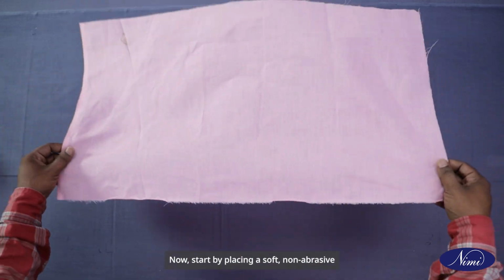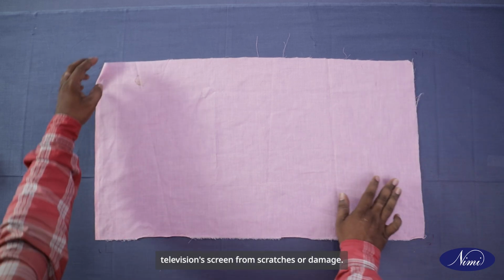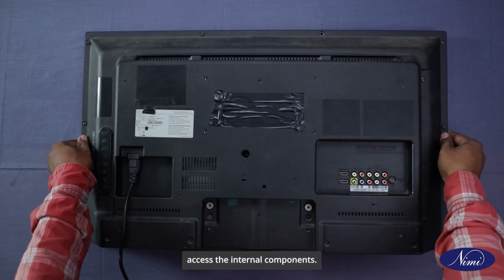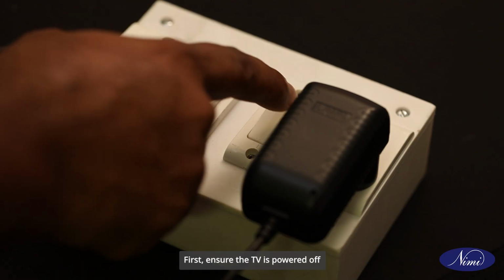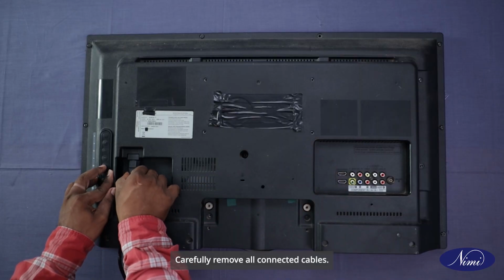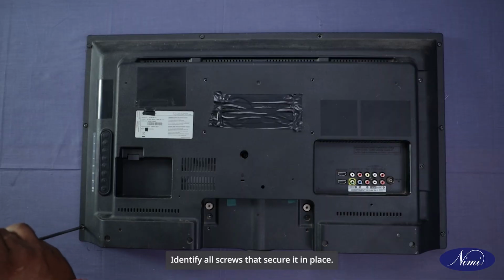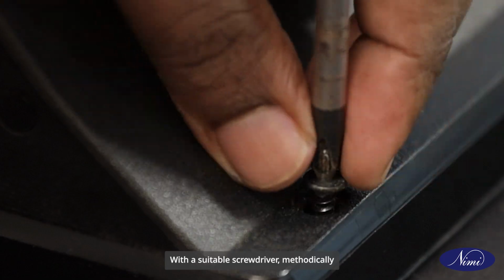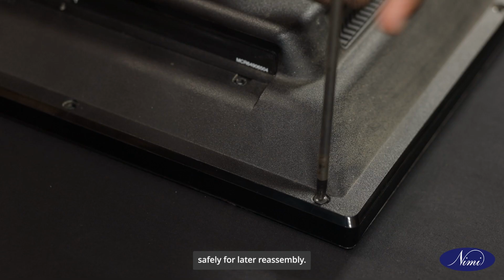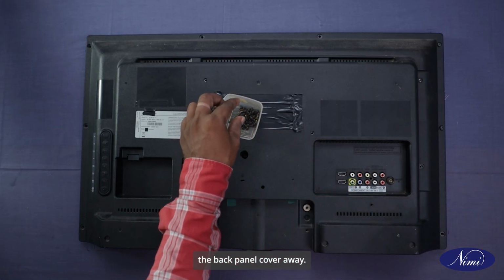Now start by placing a soft, non-abrasive cloth on the repair table to protect the television's screen from scratches or damage. Then proceed with the steps to access the internal components. First, ensure the TV is powered off and disconnected from all power sources. Carefully remove all connected cables. Now focus on the back panel cover. Identify all screws that secure it in place. With a suitable screwdriver, methodically unscrew each one, storing them safely for later reassembly. After all screws are removed, gently lift the back panel cover away.